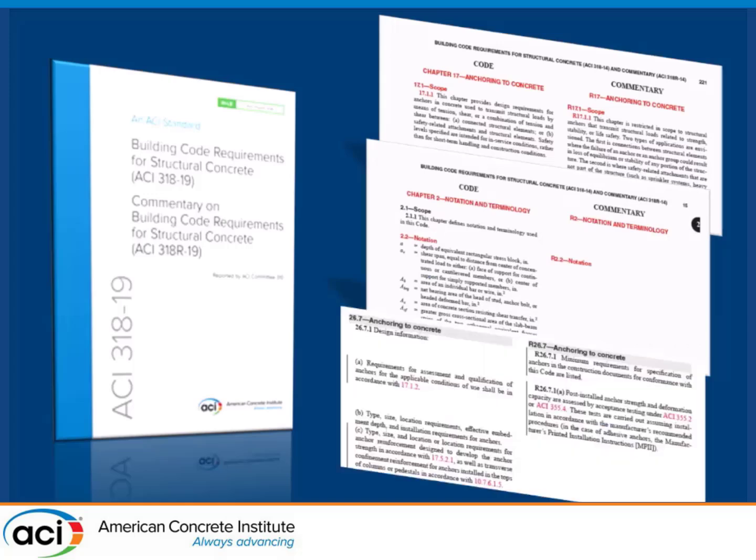And then, of course, for those who are not very familiar with ACI 318, Chapter 26 holds all the stuff that we want to put into a specification. So the specification information that is most important to ACI 318 is all shoved into Chapter 26, and yes, there is a section on anchorage to concrete. So those are the locations in 318.19 that you should go back to as far as following the code for anchorage design.